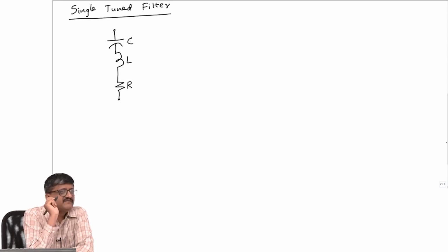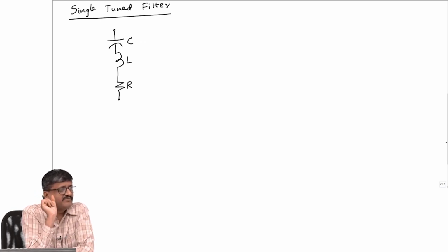Frequency keeps changing. We know nominal frequency is 50, so frequency will vary over a band. The 11th order will vary over a larger band. So the harmonic frequency is not a fixed number, it is a quantity within a certain band. That is one thing.